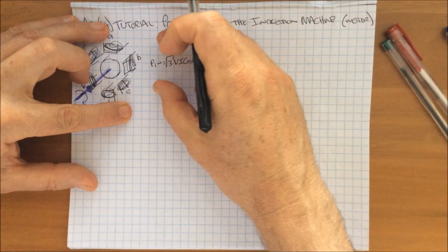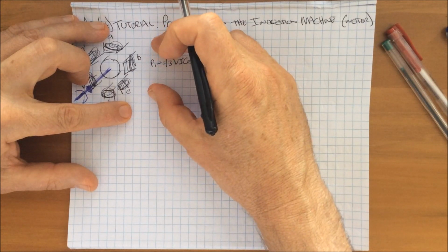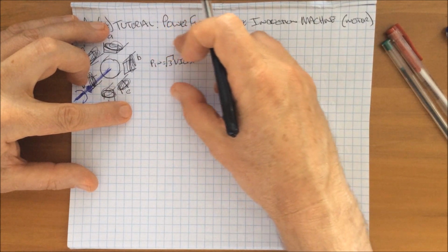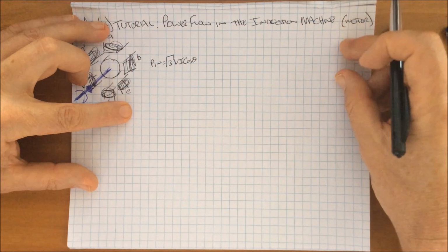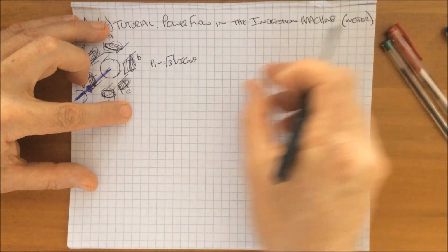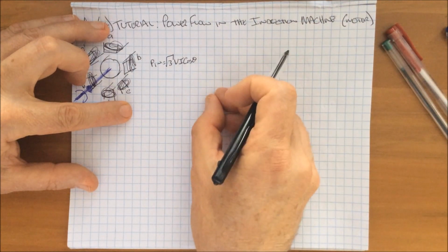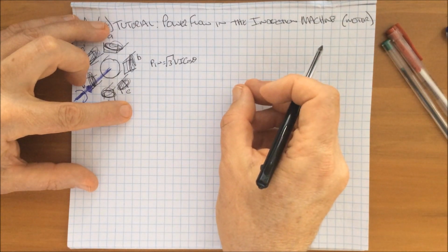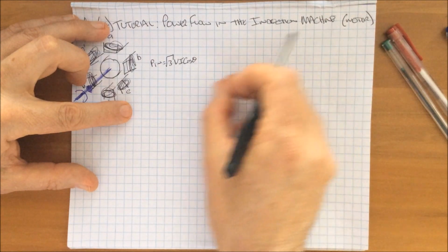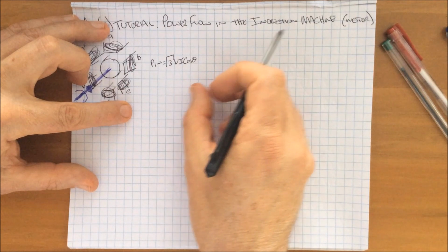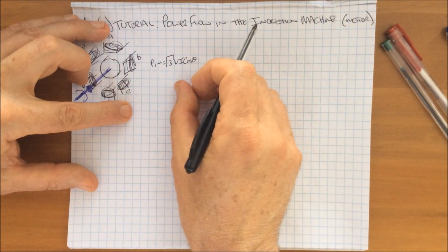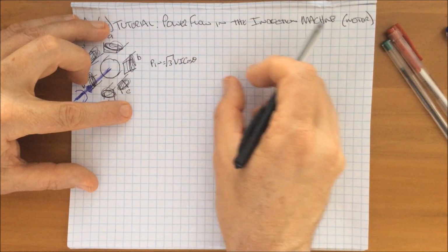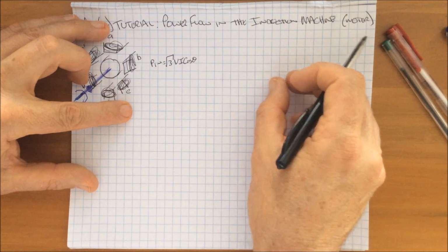So what we're going to do is we'll start here with a diagram that shows the input power coming in and then moving this way towards we get our output power over here. And as we're doing that, various powers are going to be lost and manifest itself as heat through here. For example, the I²R losses in the rotor and in the stator, and all these other sort of the windage losses and all of that sort of stuff.